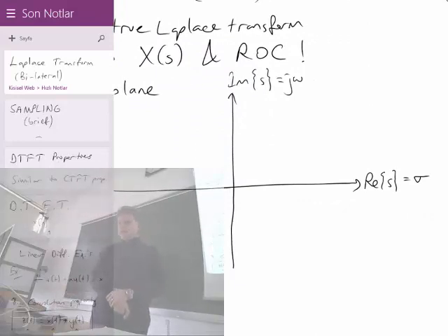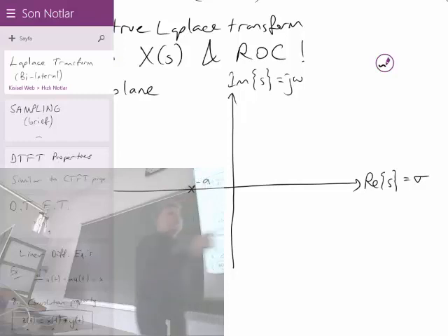And remember that a is real, whereas the vertical axis is an imaginary axis. So where are you going to mark s is equal to minus a? s is now two-dimensional, the real part and the imaginary part. So s is equal to minus a is where? It's on the real axis. Let's assume that a was positive, so minus a is here. It's just an assumption. I put a cross there, and the cross indicates a pole. It's always like that in your books. It is indicated like this. And regardless of the imaginary part, the real part being minus a is the boundary of our plane for the region of convergence.